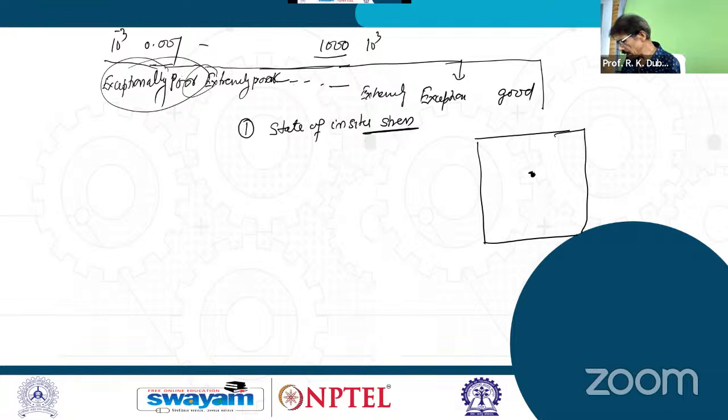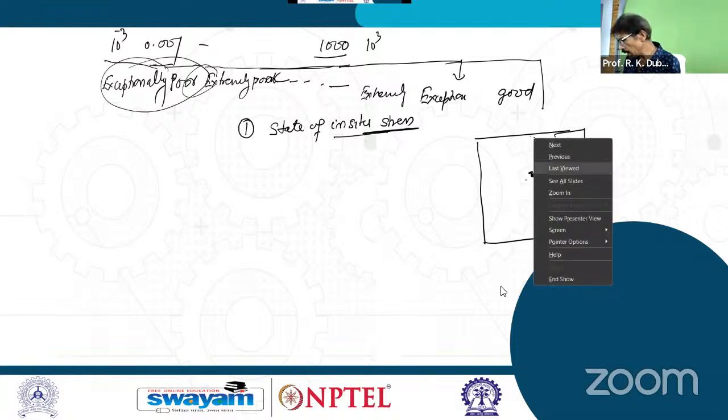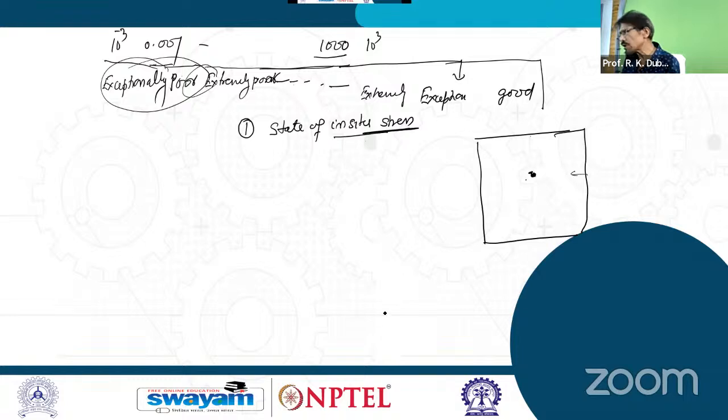What is the condition of this in situ stress? It is high, moderate, low, or very low, etc. These form due to overlying strata. So due to overlying strata and tectonic stresses and others, the stress can be resolved as vertical and horizontal, maximum and minimum: sigma h min, sigma h max, and sigma v.